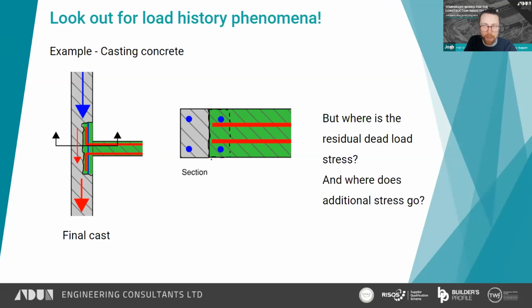This area is smaller than previous, and therefore the stresses in the column are higher in that localized area. Any additional loading into the column from above or from the new structure that is applied after casting is applied evenly over the grey and the green section of the column. But the grey part is already taking higher stresses, therefore this activity could push the column past its capacity.